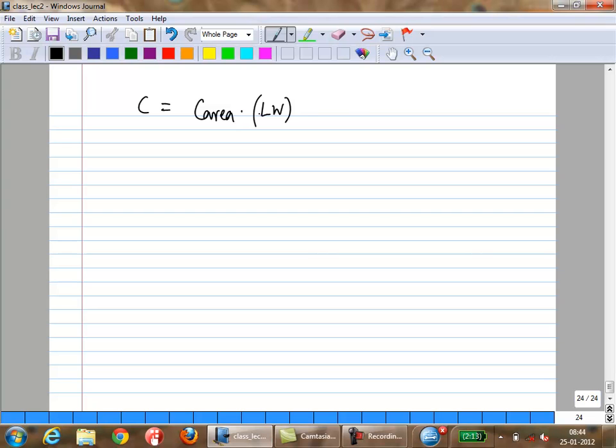But then you also have some fringe capacitance, which depends on the perimeter. Okay, because it's at the edges that you have the fringe capacitance. So now, if you try to create identical structures by just doubling the area, definitely the fringe capacitance is not going to scale the same way. So this is a source of systematic mismatch.